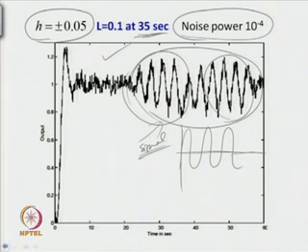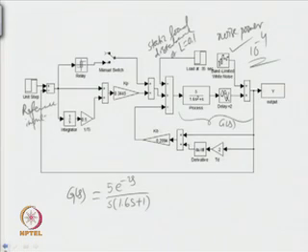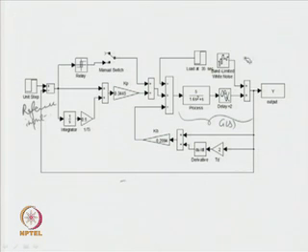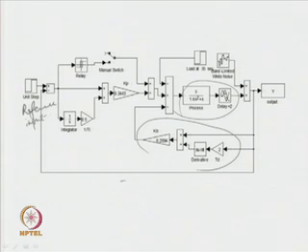identification and tuning scheme. So, let us clearly look back at this simulation diagram. What are the things we have got now? So, we have got the process which is subjected to one inner feedback controller, a PD controller, thereby giving us a stabilized process.